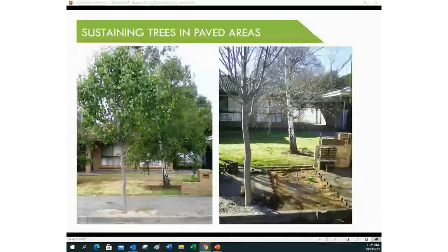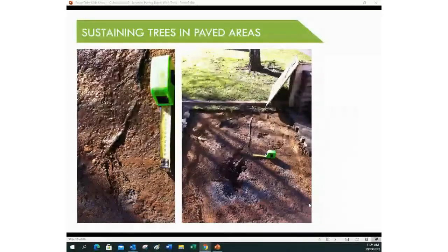And you can see here, surface root from that silver birch just creeping its way through under the pavement. If that happens to get through under a pavement, gets into some good soil, fine roots can proliferate, it can start to draw some moisture, that root will thicken and lift the paving. That's fairly standard. It's guaranteed to happen.